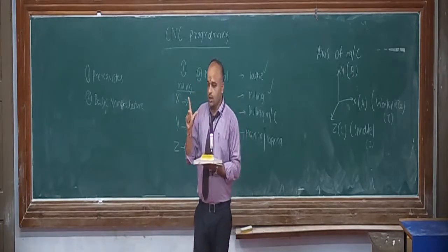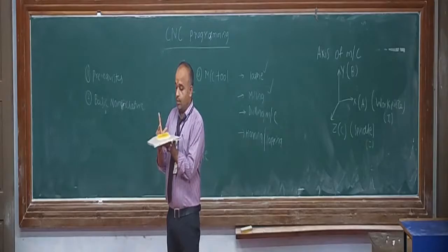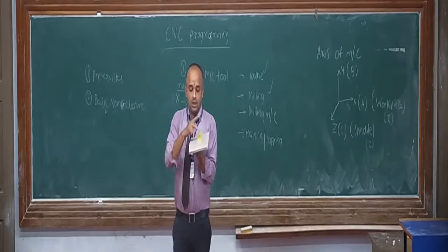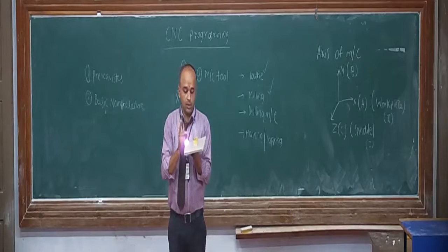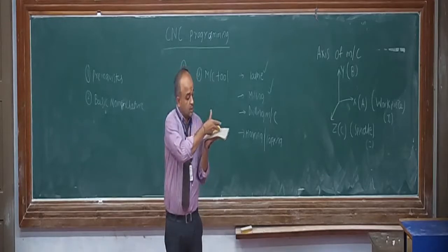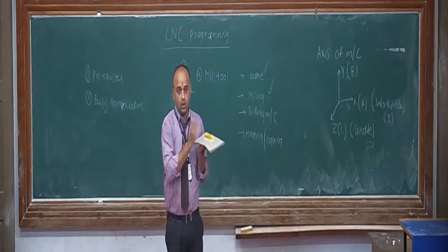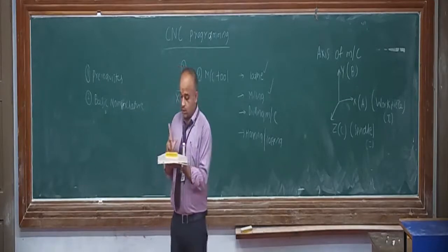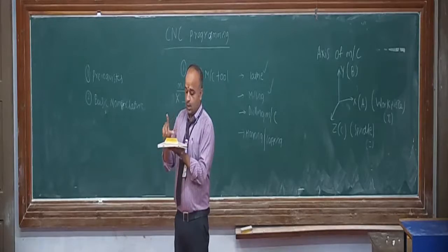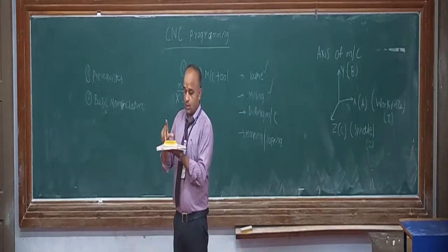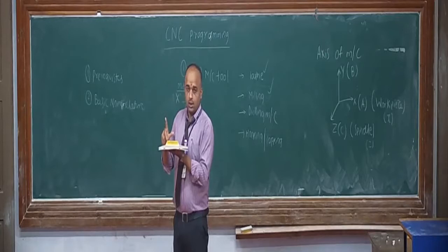In this condition, your spindle will be like this. This is the bed. The yellow color part which you are able to see here is nothing but the workpiece on which I am going to do the operation. Now, just imagine that this is the face on which you are going to have some drilling or boring operations. If your spindle is z, the x axis is nothing but the length, the width is y, and the height is nothing but z.